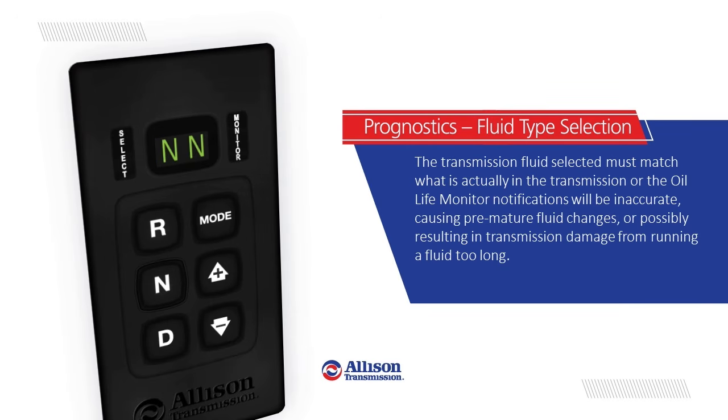The transmission fluid selected must match what is actually in the transmission, or the oil life monitor notifications will be inaccurate, causing premature fluid changes or possibly resulting in transmission damage from running a fluid too long.